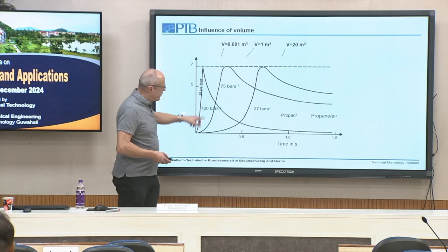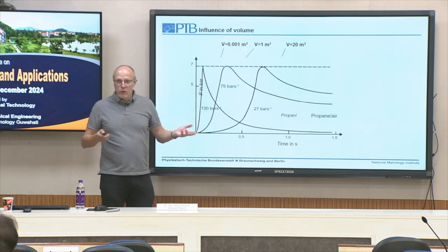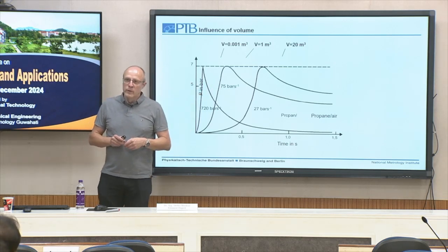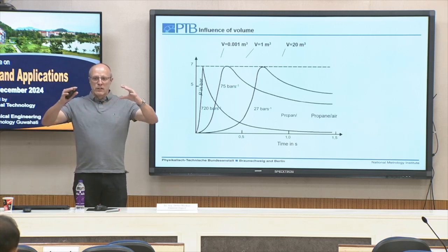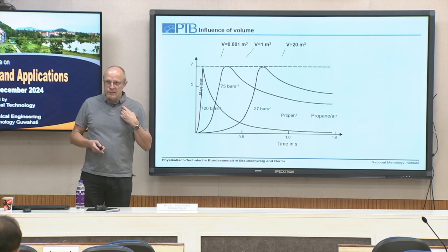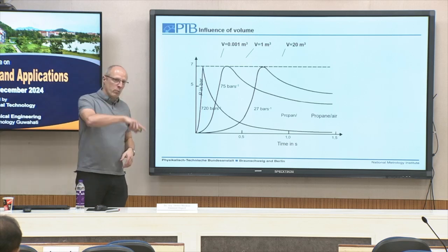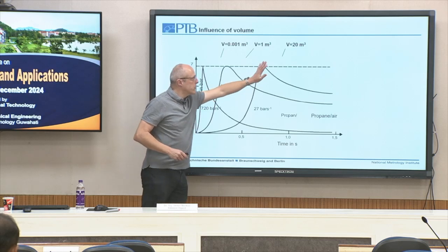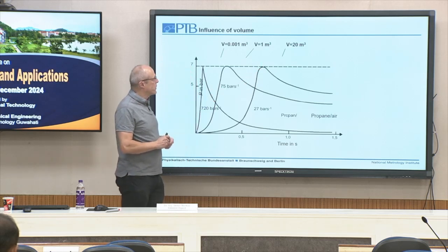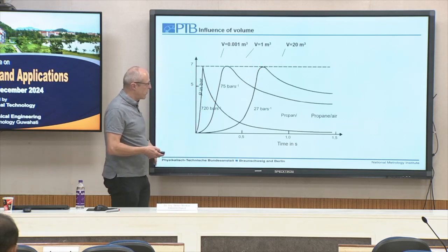But of course, the pressure rise strongly depends on the volume, because we start with a very small ignition volume, which then spherically propagates in our system, and the ratio of burned to unburned gas is of course different in this large vessel compared to the small vessel.